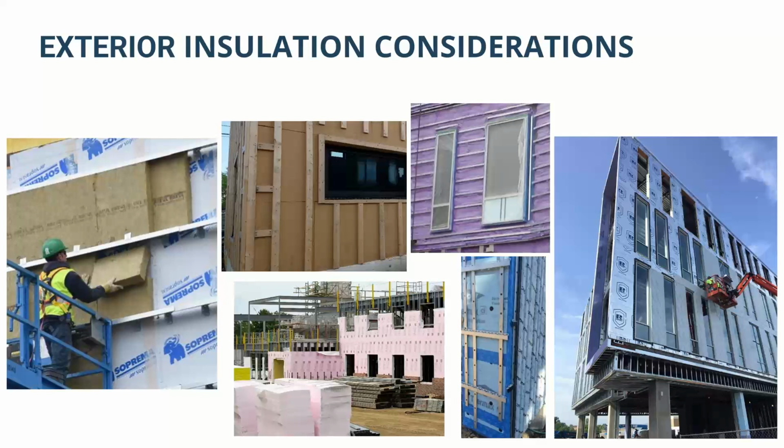So this is going to impact how the wall is going to perform and manage water. So things like foam plastic are going to be much lower vapor permeability than mineral fiber. But again, lots of different types here. And they have also not just different permeability, but different thermal performance. So different amount of R value per inch. And they also may have, well, they do have quite a bit different properties in terms of combustion and smoke development. So that's another thing that needs to be considered there for exterior insulation.